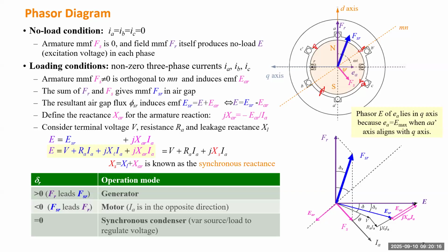So this one is simply equal to the field current multiplied by the number of turns. FR is simply the field current, which is on the rotor, the magnitude of current multiplied by how many turns you have on the wire. So this can be a constant. And this one will generate magnetic field, and the magnetic field will revolve inside of the generator. And that magnetic field will induce this voltage, E, which is the excitation voltage.